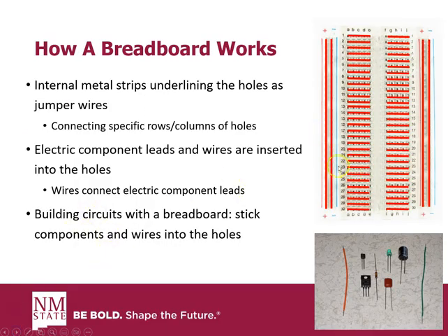Now let's go back again to the breadboard and see how it works. So a breadboard is a solderless device used to build and test electronic circuits. The key to understanding how a breadboard works lies in its internal metal strips underlying the holes. These strips act as jumper wires connecting components.